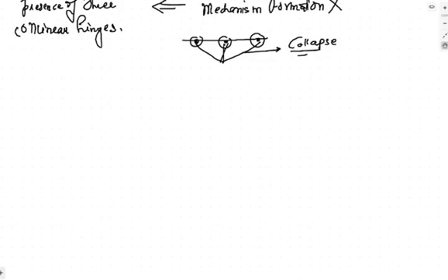This is mechanism. तो इंटरनल स्टेबिलिटी के लिए क्या क्या होना चाहिए? एक तो आपका प्रॉपर अरेंजमेंट होना चाहिए, मैकेनिज्म नहीं होना चाहिए। दूसरा चीज, there should be enough number of members. अगर आप बात करते हो मेंबर्स की इंटरनली, तो internally there are two types of members which can be classified. One is pin jointed member and another is rigid jointed member.